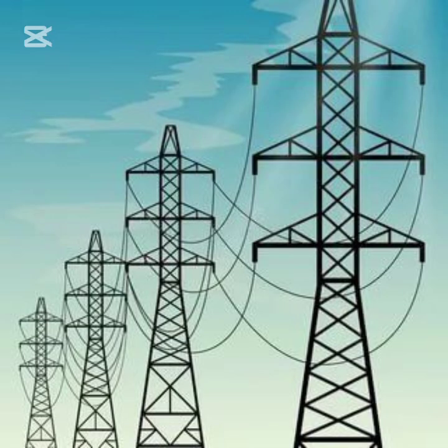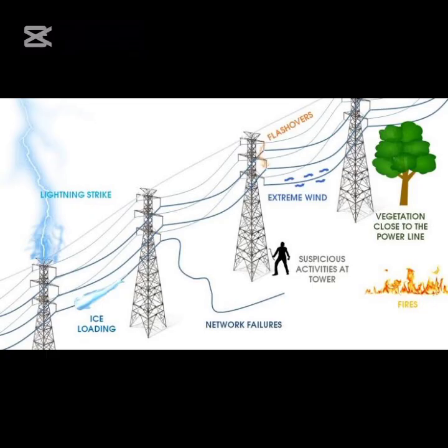2. Loss of mechanical strength. Loose sag may impose excessive stress on conductors and their supports, increasing the likelihood of mechanical failures. 3. Conductor damage. Excess sag can cause swaying of conductors, raising the risk of contact with other conductors or objects, potentially resulting in damage, short circuits, or outages.